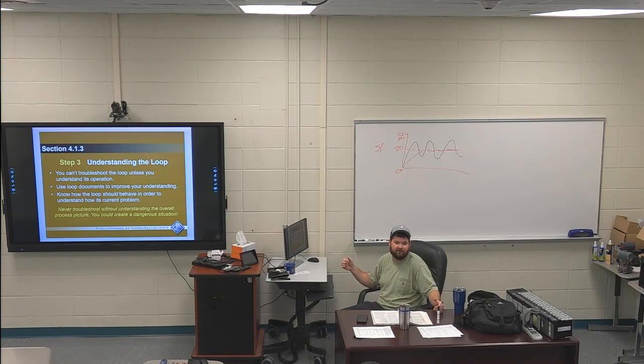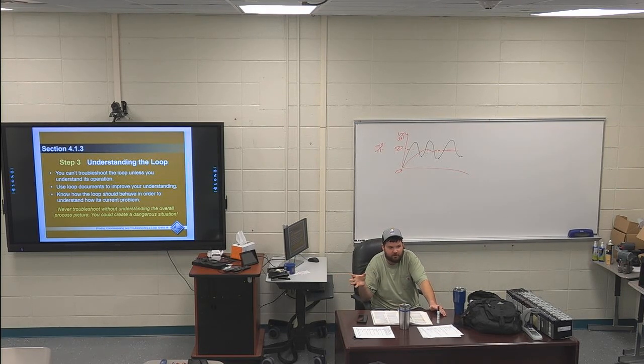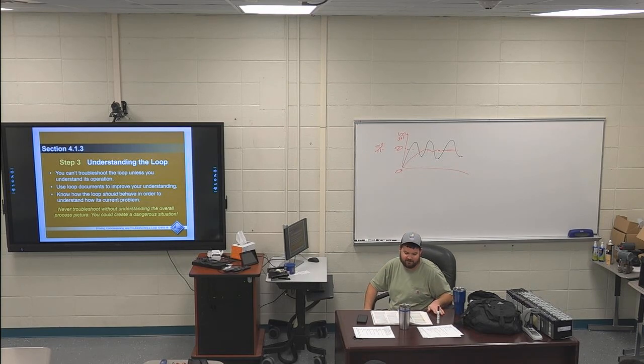It might not be obvious to an operator what's going on, but doing a mechanical or visual inspection, you might see that somebody busted the conduit off the side of that, and the control wiring is busted off, something like that. Go to where the problem is, and start at one end or the other, like the power supply, or all the way at the other end.